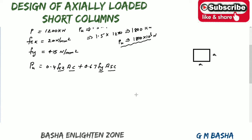So this is the gross area, assume Ag. The overall gross area consists of the area of the concrete and the area of the longitudinal bars, that is the area of the steel. So gross area will be equal to area of the concrete plus area of the steel.